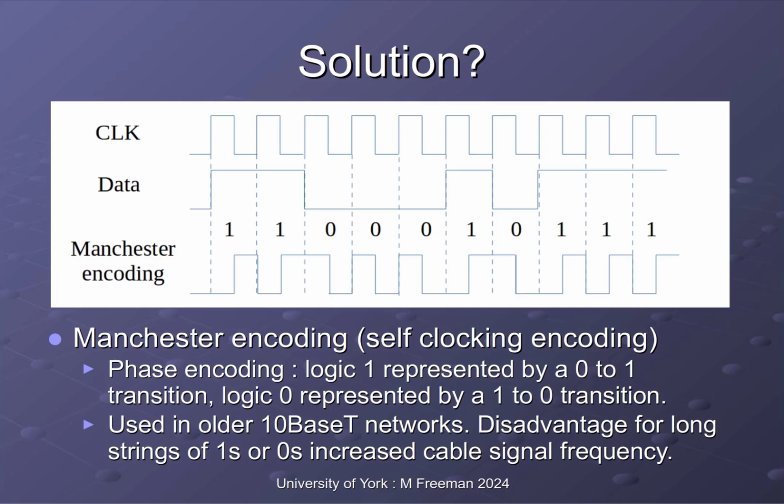A voltage will be induced into that cable, and you do not want those cables directly connected to the electronics in your computer, as obviously that will cause every computer on that network to blow up. So therefore we want to isolate the electrical signals used to transfer our data on the network from the electrical signals in our computer. And to do that we typically use a transformer.